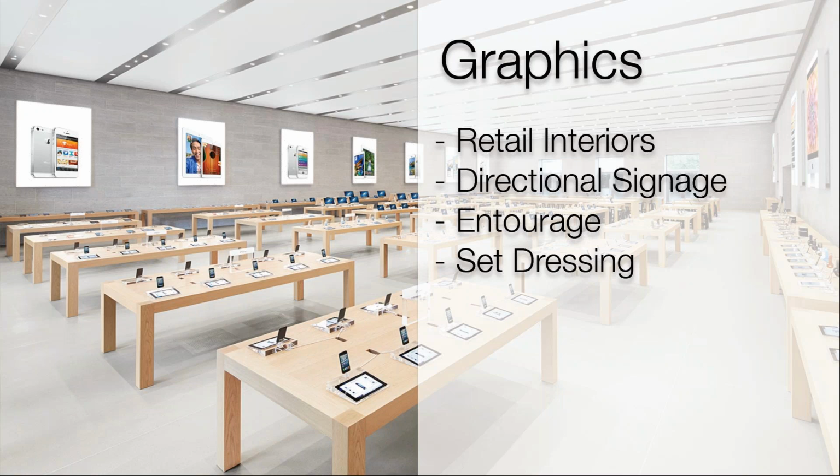Now, the great thing about graphics is they're really just materials in Revit, and you can use materials to communicate an enormous amount of geometry detail, much like game engines, without committing to building a lot of detailed geometry. So think about an expensive piece of equipment or a very expensive appliance. You can spend a lot of time building all of those reveals and all of those buttons and all of that detail and never get to a natural looking component when you view that in a real-time environment.